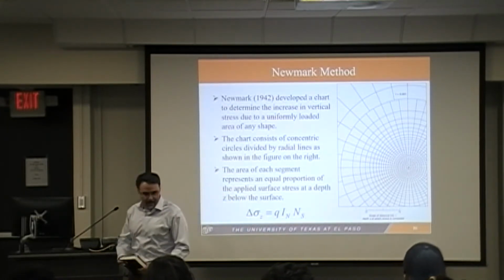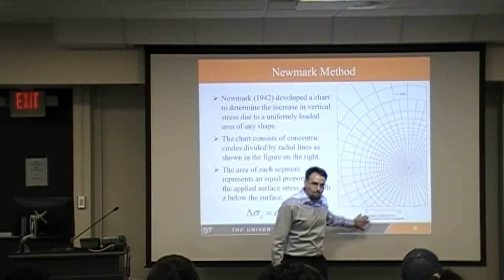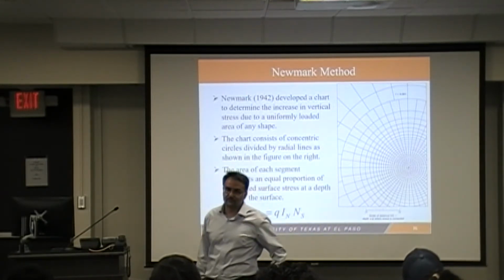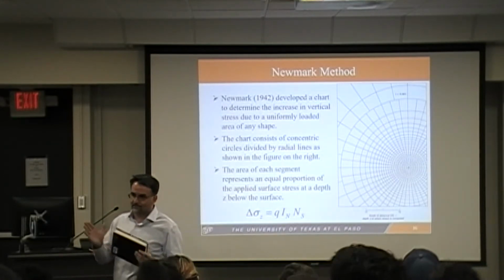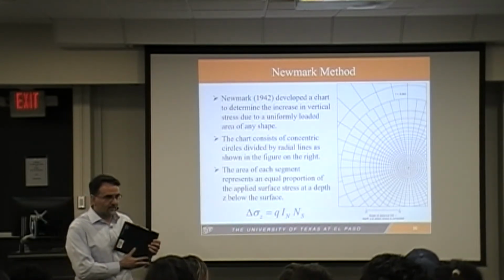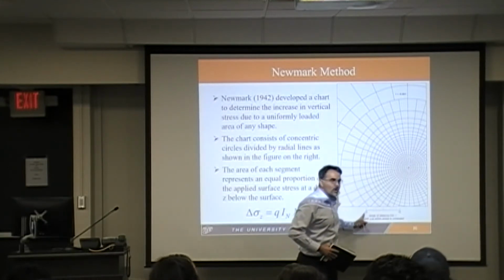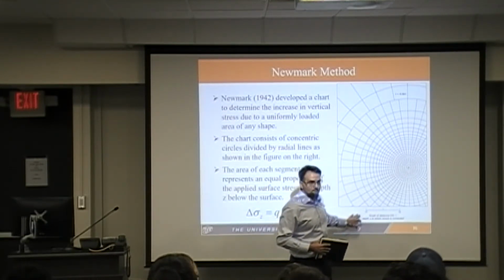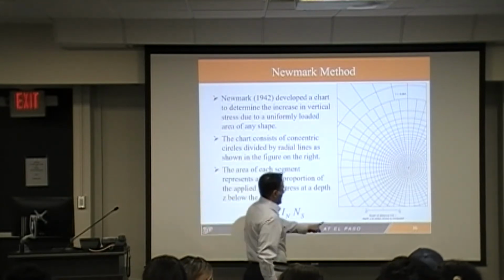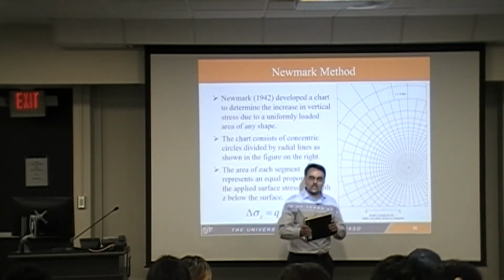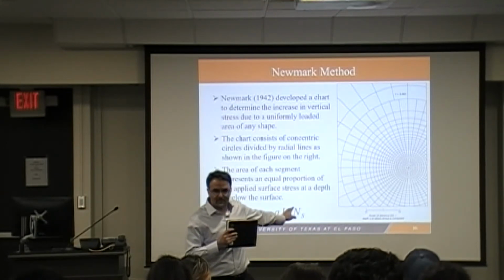Alright, so first of all, what we have in this plot is an I value and a scale, that OQ, as you can see here. So the first step is to rescale your geometry. Let's assume that I'm looking at a rectangular shape footing in this case. First step is I have to set the scale to the depth that I want to calculate the stresses at. Let's assume that I want to calculate the stresses at 5 feet down the depth. So I set this one as 5, and rescale my foundation based on the depth scale.